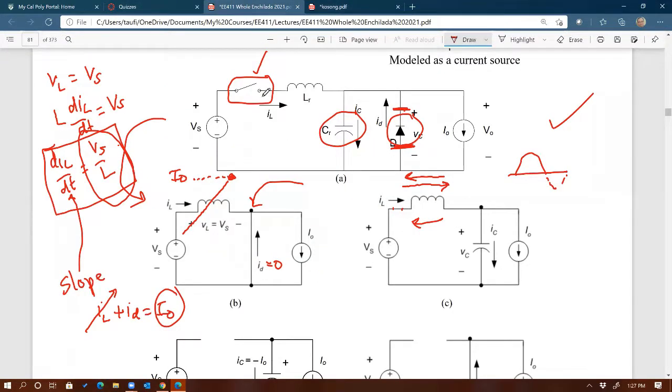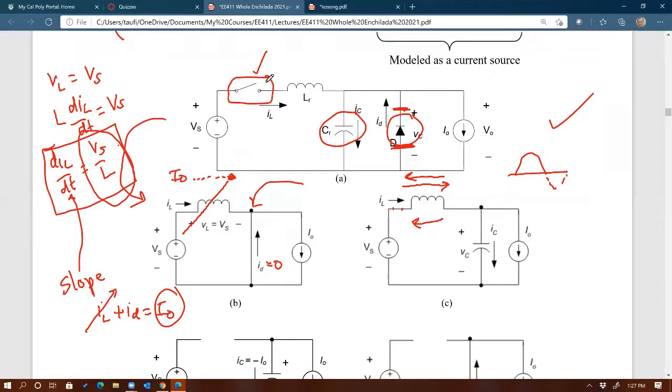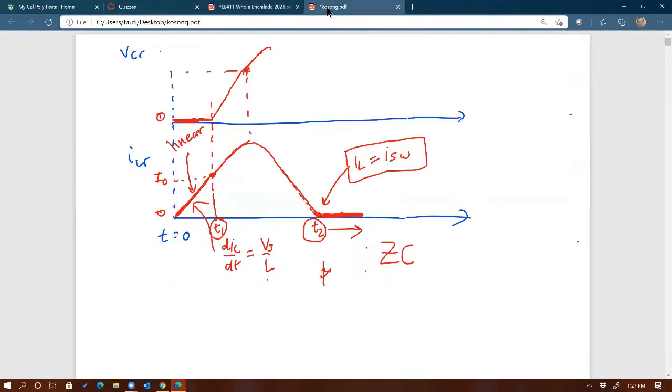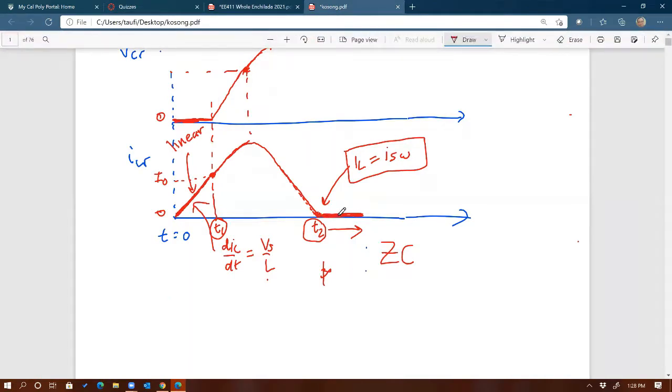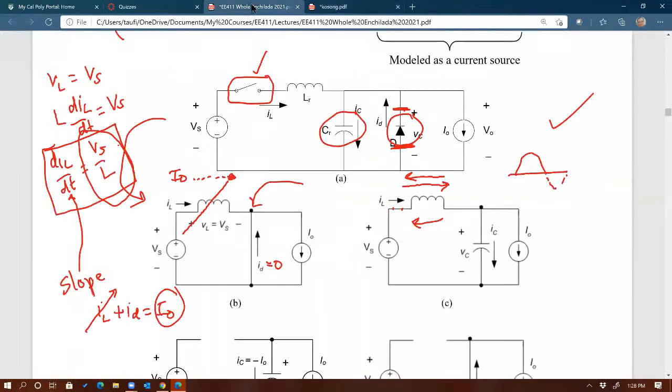Well, because the switch is unidirectional. Oh, unidirectional. Yeah, that's right. That's why it is important to have a unidirectional switch. Otherwise, this won't work. So because of the unidirectional switch, that current stays at 0, and it basically automatically turns off at T2, like it's effectively off.